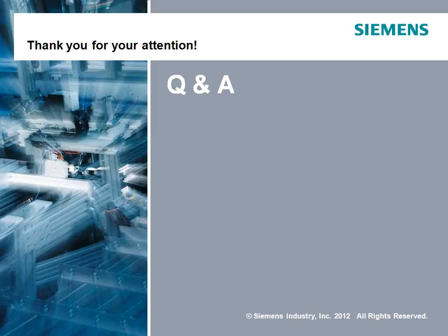Okay. Next question. EN 954-1 is withdrawn, replaced by EN ISO 13849-1. As a machine tool builder in the U.S., how am I affected? Interesting question. EN 954-1 brought the concept of safety categories B, 1, 2, 3, 4 to the table that NFPA 79 also utilizes.